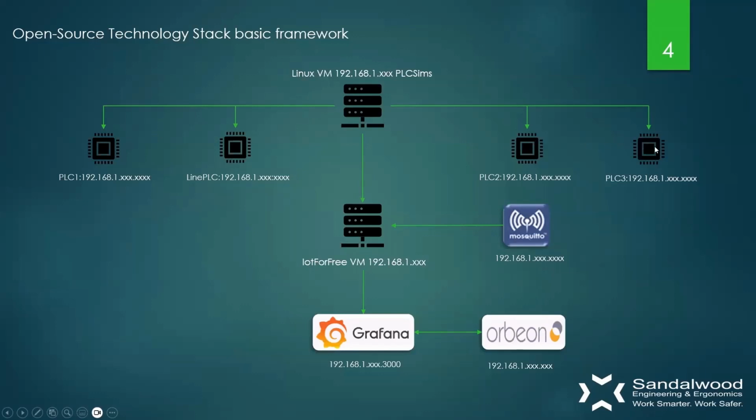These PLC simulators are simulating machine properties such as temperatures, pressures, speed, fault characteristics, and so on. The broker allows the agents on the relational database to subscribe to them, allowing for their consumption to the open source database. Within Grafana, we can utilize the MQTT database plugin. And once that's fully configured, we can subscribe to the broker's topics and visualize that data within Grafana.